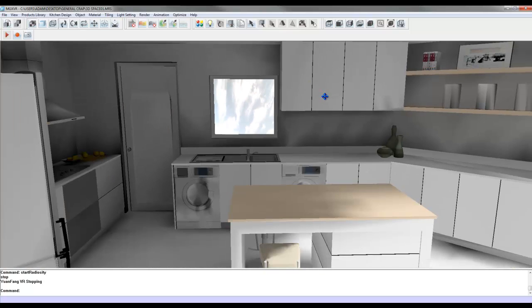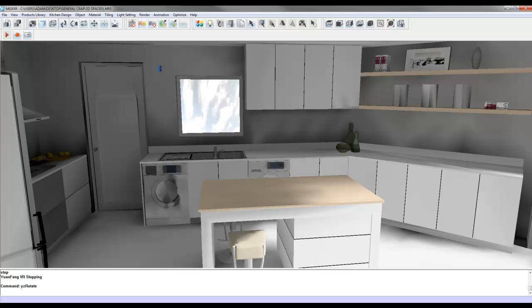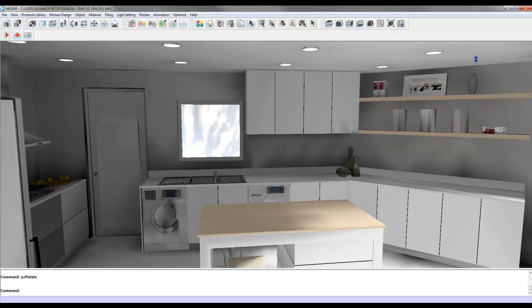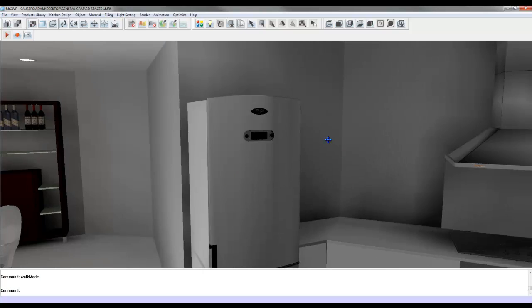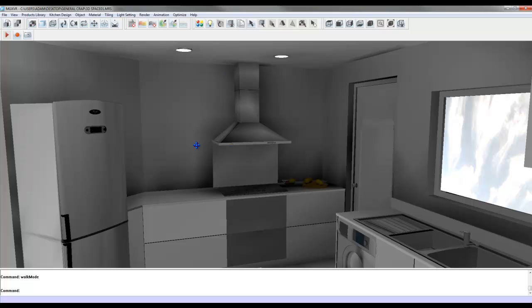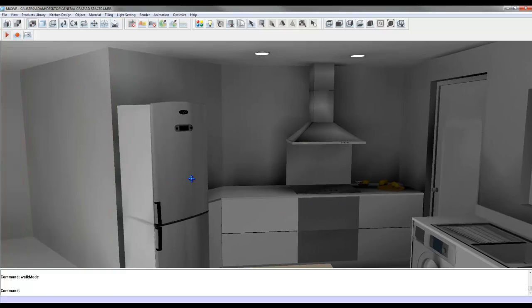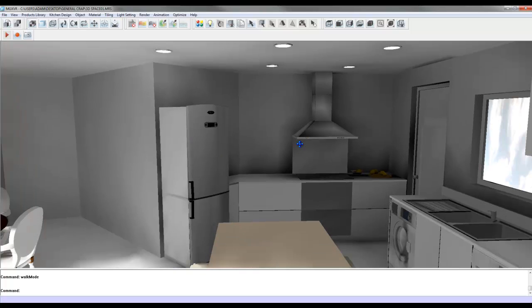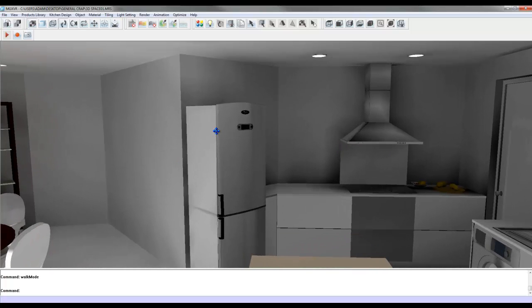Our problem area is going to be the kitchen, and the reason for that, the ceiling seems to be fine. The problem is that we've got all these other things that have popped onto the wall. So you've got cabinets there, splashbacks of the kitchen counters, and then on the left hand side here we've got the whole extractor unit as well as the sink and all of that. So now we're going to use an option called Optimize Surface, which basically rearranges the mesh to fit into any objects that are intersecting it. So let's just take a look at how that works.